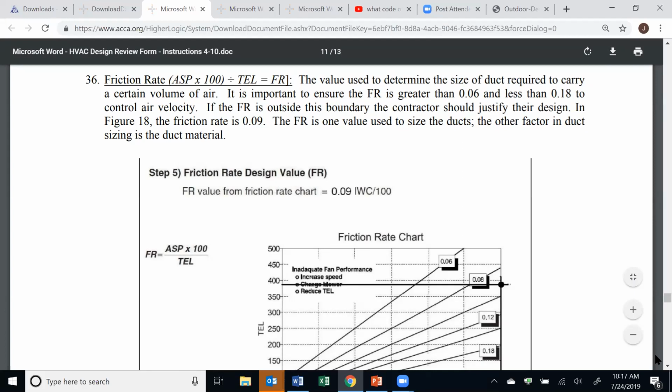So the short answer is no. I think if you see a very high number, that tells you that fan has to work really hard to move the air. And if energy is a concern, you really want to see something a lot lower on the curve.